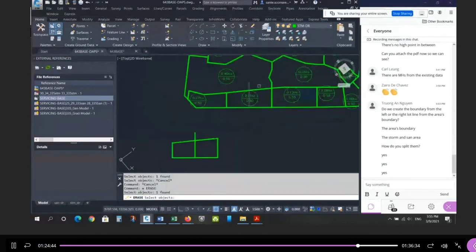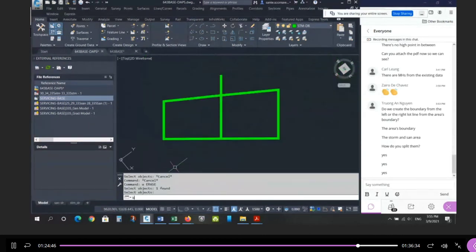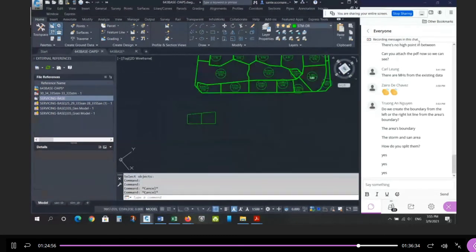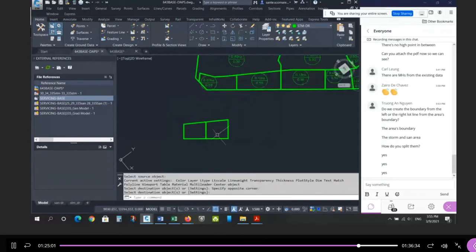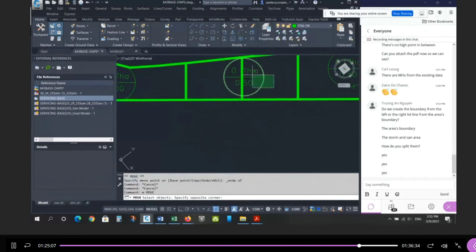Well, I'm going to use my boundary command, like I showed you before. BO for boundary. I'm going to pick, split it here and here. And now I can get rid of this and this, and now I have two parts. Same command as before, remember the boundary? And then you can put it on the same layer with the same style. Delete this one, put this back where it belongs, endpoint to endpoint. Move this bubble over and make a copy.